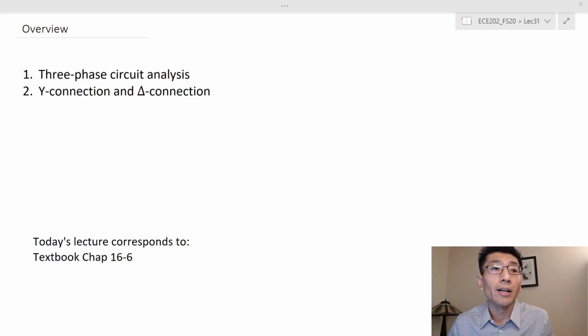Hello everybody. Today we're going to talk about the three-phase balanced system, the circuit analysis of this. Last lecture we talked about what the three-phase balanced system is, what the positive sequence and negative sequence are, and the line voltage, the phase voltage, or line-to-neutral and line-to-line voltage, all these basic concepts. So today we're going to look at the simple techniques to analyze the three-phase circuits.